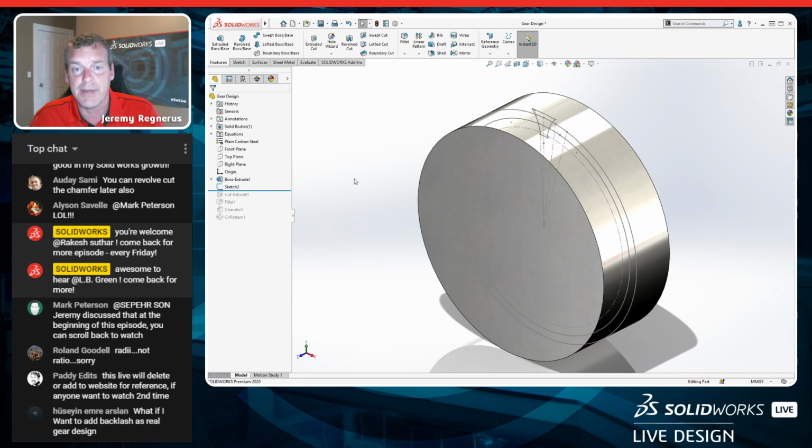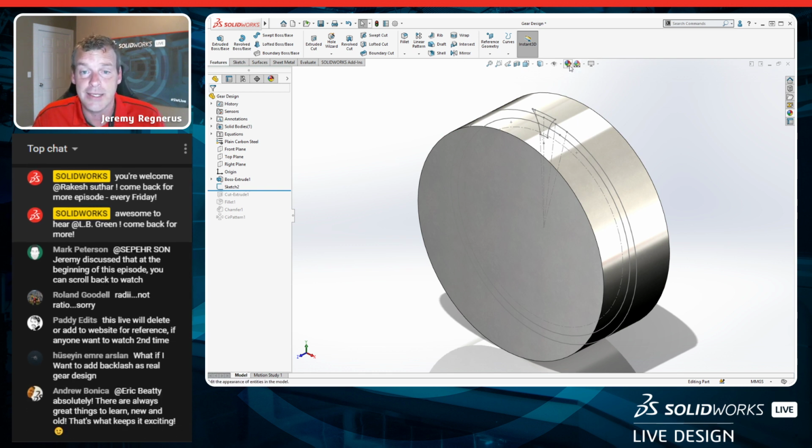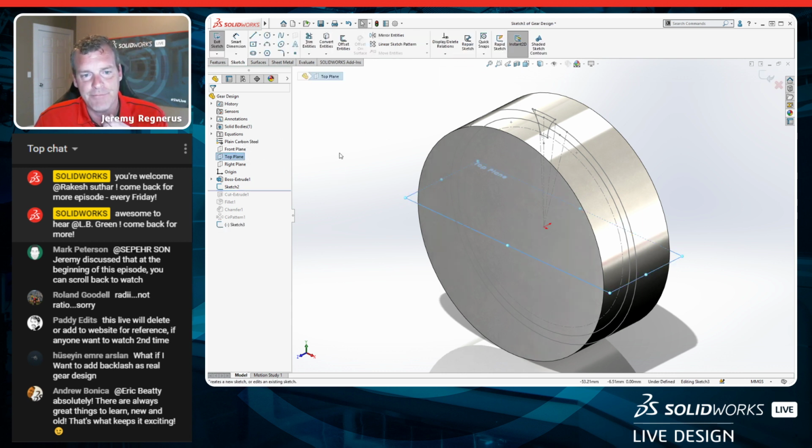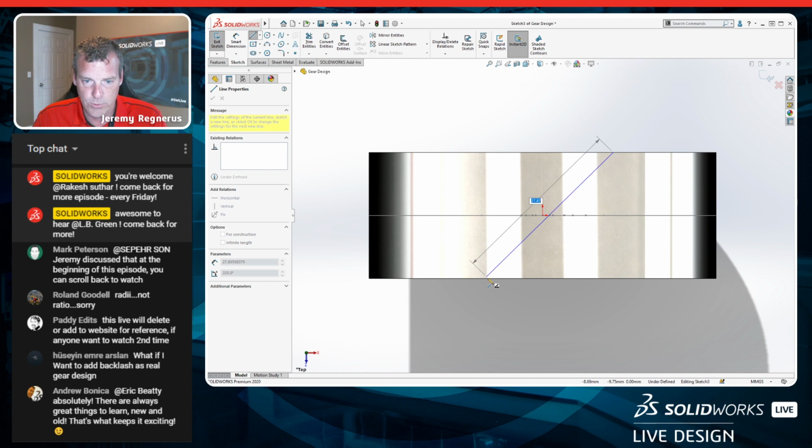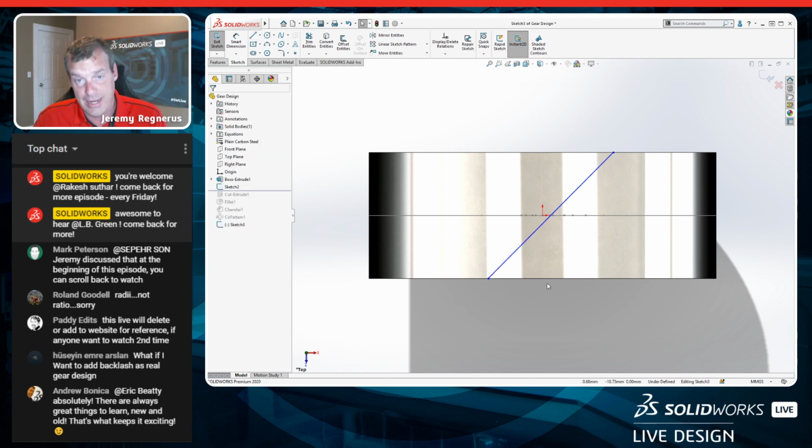Let's turn my sketches back on with Shift S, which is my key, or from the drop-down menu up here. What I'm going to do is I want to create this at an angle right here. So how am I going to capture this angle? Well, if I look at this from the top view, I'm going to go normal to. So again, here I'm going to use mouse gestures. See how I have normal to set as a standard mouse gesture I use all the time. We're simply going to draw a line that's going to represent our helical gear angle.